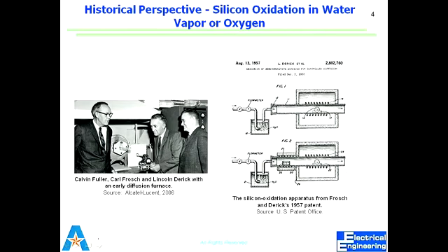So I just said depositing a nitride layer. You would seldom hear growing a nitride layer. Why is that? We discussed this growth versus deposition last time. We can grow or deposit silicon dioxide, but we can only deposit silicon nitride. What does that mean? We are adding silicon oxide. So we can do some chemical reaction and convert silicon into silicon dioxide, but we cannot do an easy or straightforward reaction to convert silicon into silicon nitride. So what we do essentially, we always deposit silicon nitride.